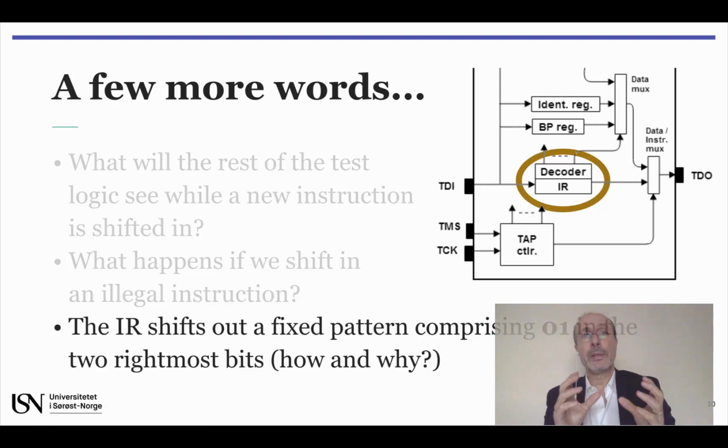Well, this requirement is important because it toggles every TDO to TDI interconnection, since TDO is initially driven to 1 and then driven to 0. If there is any short or open fault involving the test access port pins, these 0-1 sequences will not show up at the port TDO, and in that case we know that something is wrong with the boundary scan chain itself. This is what is called the integrity test of the boundary scan chain.